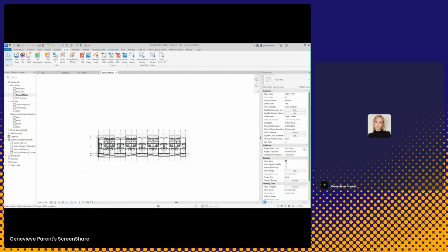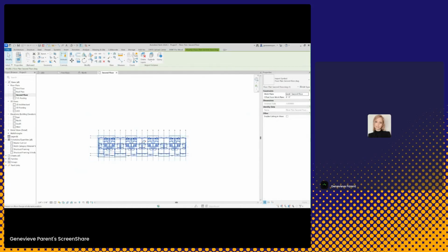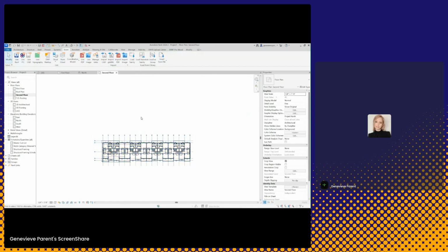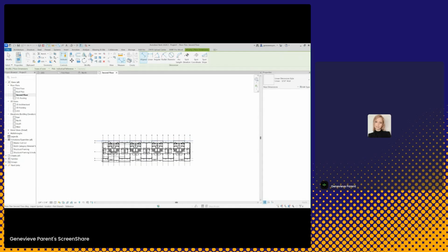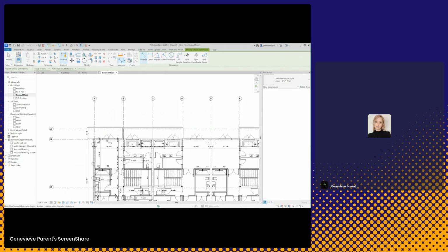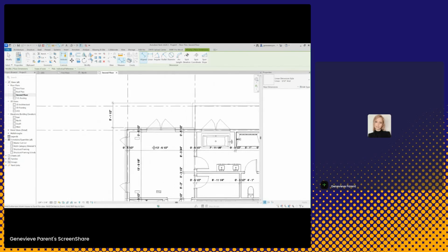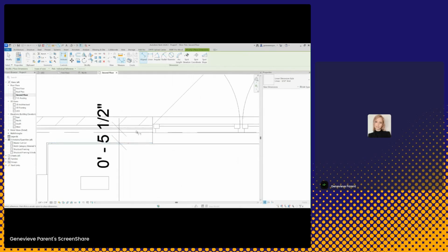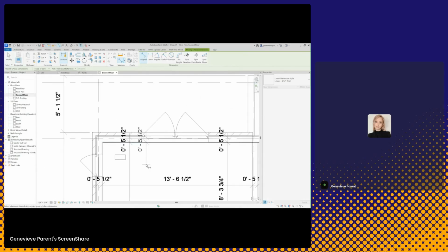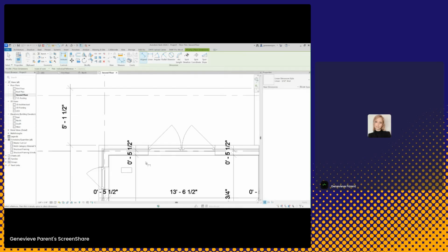It's okay if they're not stacked properly. There's no problem with that because you can just move them when they're brought in. Now, when it comes to AutoCAD, generally speaking, they should come in to scale, but you want to verify that just to be sure, just to make sure everything's fine. You're going to want to check these dimensions to make sure you don't have to scale it. In this case, we're good.